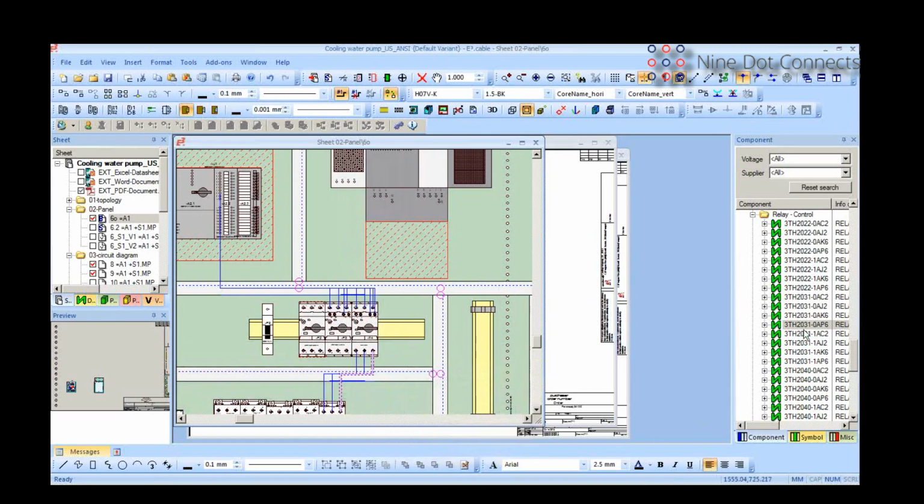Now the length, even though the tool is a 2D design tool, as far as the panel components are concerned, it does have 3D information. So it knows the height of that connect point from the base. So now it can calculate, okay, I need to go down to the base back plate. I need to go to the wiring trough. I need to come up to my destination and then come from the back plate up to the height of that connection point. And that's how we can get the true length from the panel, even though as a user, we are working in the 2D mode.